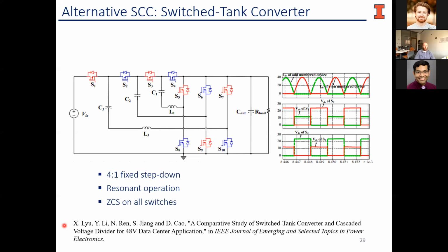It's missing a few components. It's interesting that they renamed the cascaded resonant converter to something completely different while still citing the original paper. But this is an alternative topology that we can look at where, again, they've used more capacitors and more switches. There's no transformer here. They're still getting soft switching because they've introduced these inductors that allow them to get this resonant switching. And so this turns out to be a very nice counterpoint to the other operations.